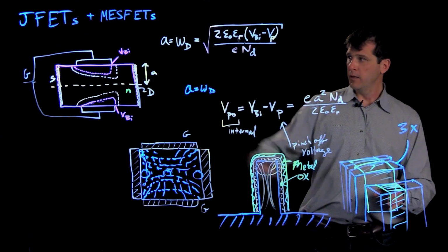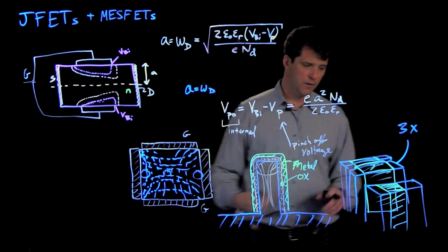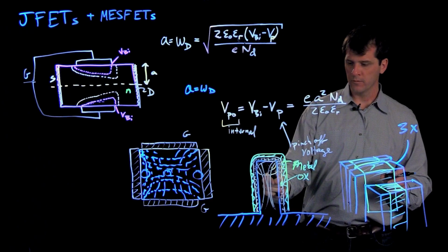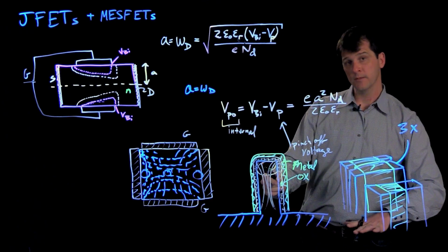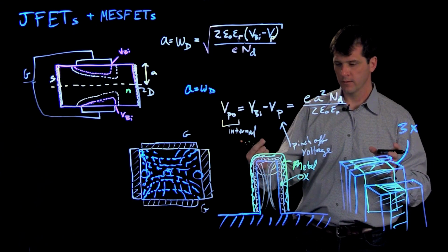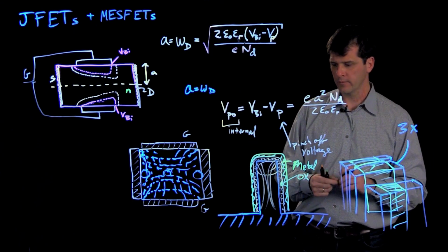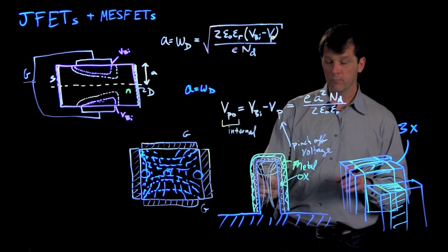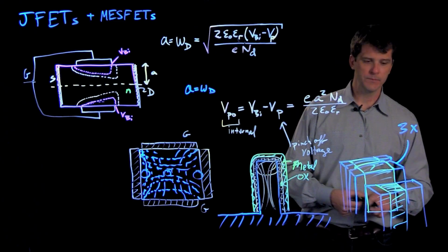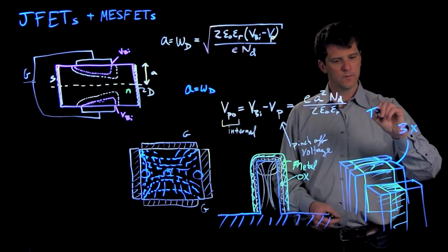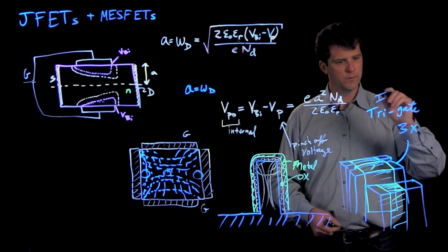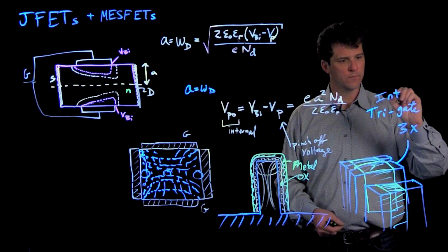And then compared to the flat topology transistors, we've greatly increased the control over the channel and reduced the leakage, which will help in power consumption quite a lot. If in the off state there's less and less current, it means that there's less and less power draw by the integrated circuit made up of these transistors. So again, that's called the tri-gate, and I believe it came out in about 2011 from Intel.